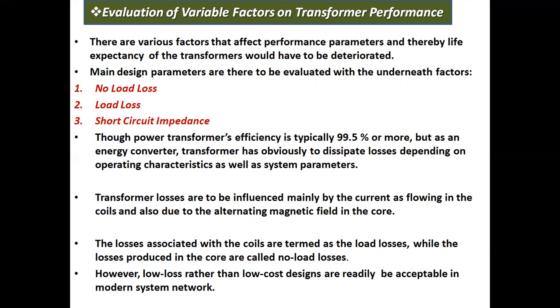Transformer losses are influenced mainly by the current flowing in the coils and also by the alternating magnetic field in the core. The losses associated with the coils are termed load losses, while the losses produced in the core are called no load losses.